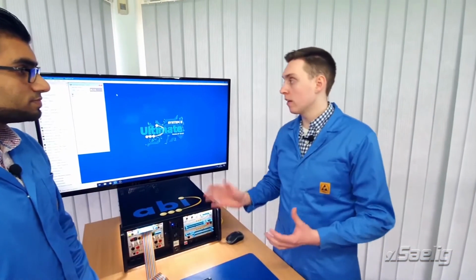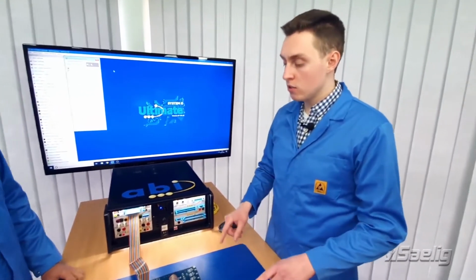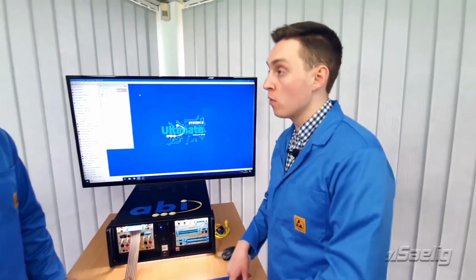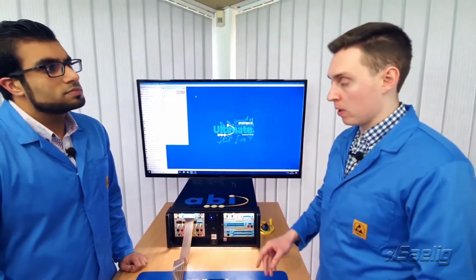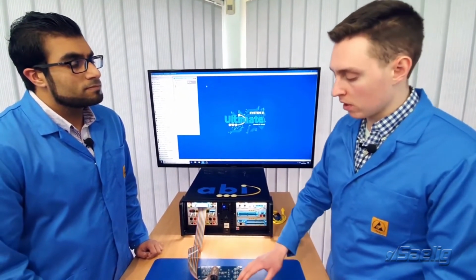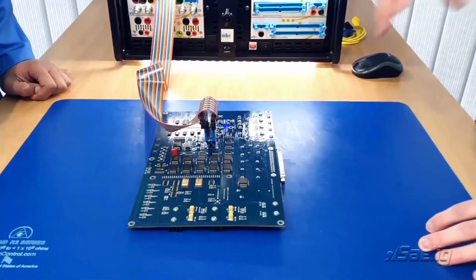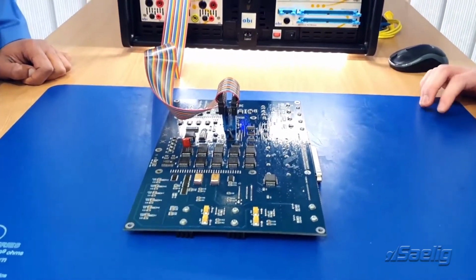Okay, of course. So in the last episodes we talked about using VI to look between one point and another. Usually we were using that to look either over a component or a series of components from the start of those components to the ground. In this case we'll be using matrix VI, where we'll be looking at from each pin and using all the other pins as a reference, so we get to see the complete mapping of that IC.